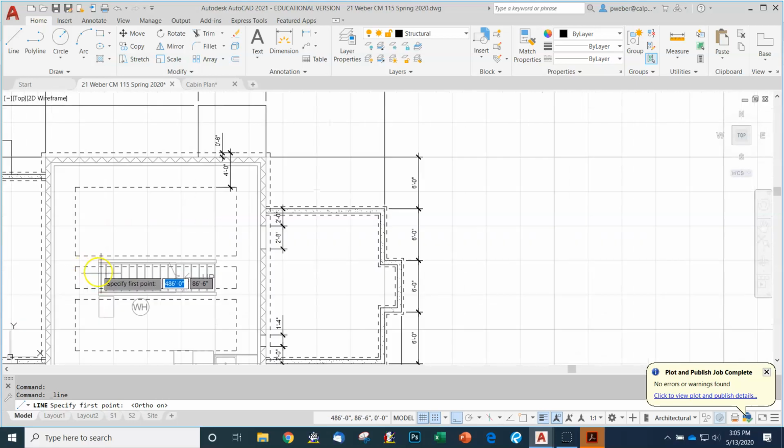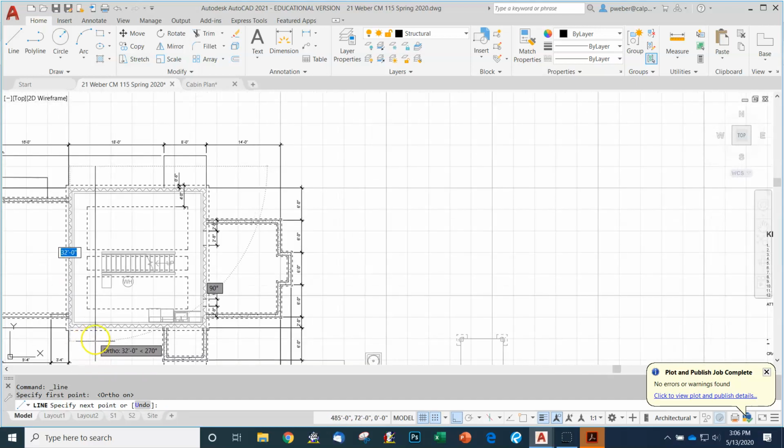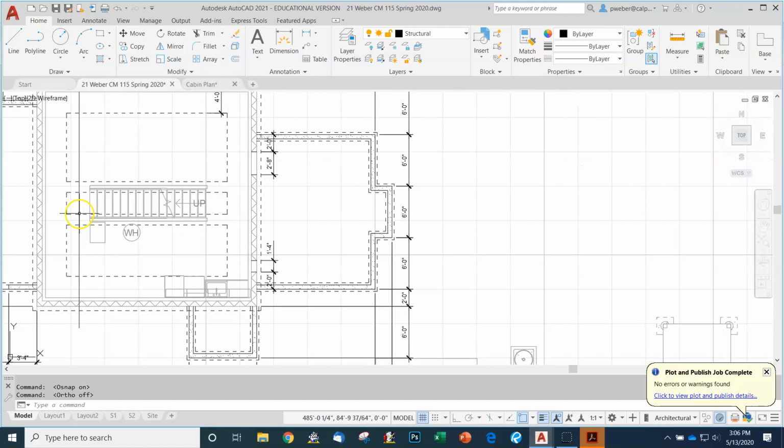Maybe it's just a couple feet out in front of the staircase here. Let's just come up to here and about to here, come straight down. A little bit from the backyard, a little bit the front yard. Perfect. Okay. So this is just a point I'm going to snap to. But I'm going to turn off Snap. I'm going to rely on OSNAP. But I don't need ortho. And I'm going to put a string of dimensions across here because somebody needs to know where this footing is.